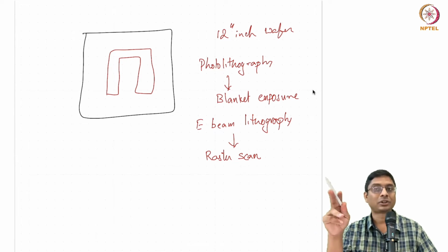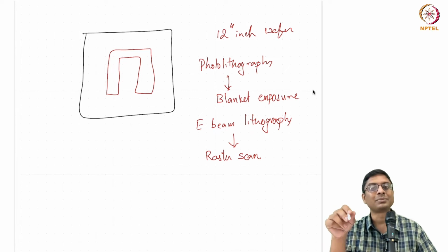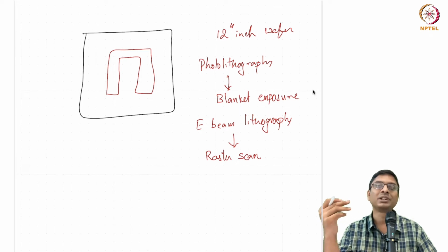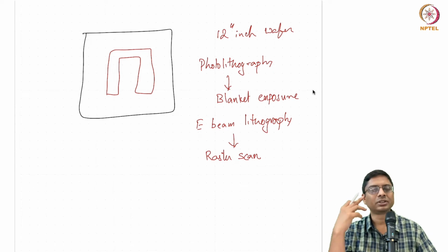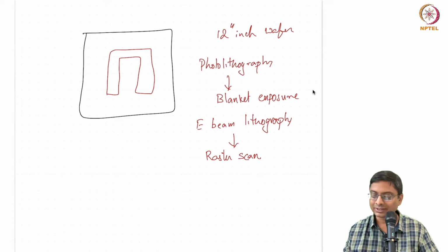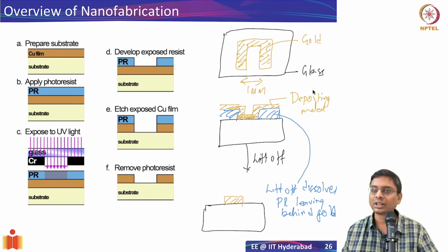But an electron beam is still used when making the mask. You can do all these techniques, but a mask also is required, right? Who makes the mask? With an electron beam machine. And that is why a mask is actually very, very expensive to make. The state of the art, let's say NVIDIA chips and things like that, the mask itself might cost about $40 to $50 million to make a mask set. It's quite expensive, so companies actually have to think about a lot of cost. So electron beam that way is okay as a research tool, but not a production tool. We can make masks, but not more than that.